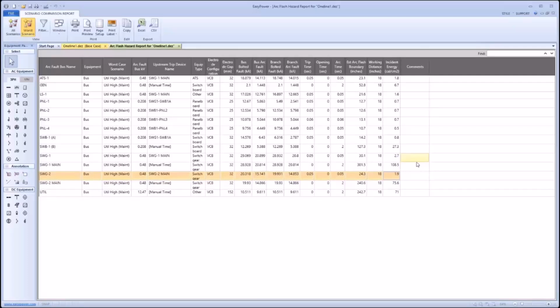So, you know, in a normal scenario, you'd probably have those breakers set higher than that. Maybe your incident energy is, you know, much higher than it is here. You might see a pretty big reduction in incident energy. You can provide a table to customer for, you know, separate incident energy values, separate ArcFlash values for maintenance mode settings on, and potentially maybe even label for those. Just depends on your processes and standards.